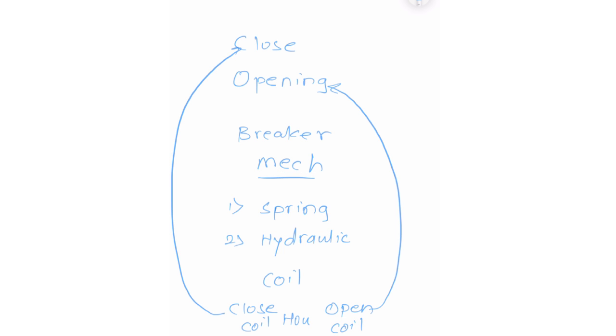How this closing and opening is achieved depends on when the coil operates, which is controlled by our control drawing. In the last video, we saw that a breaker closing coil is used to close the breaker. Negative is continuously extended, positive will be extended through various conditions, right? And these conditions put in series will determine the logic of breaker closing. Today we will see each case in detail.